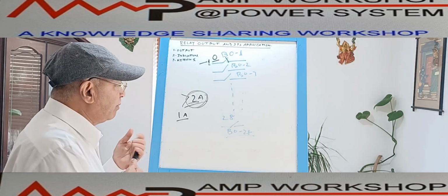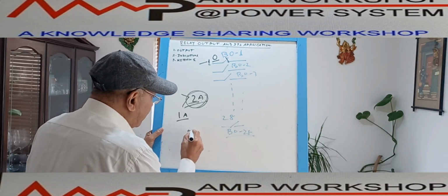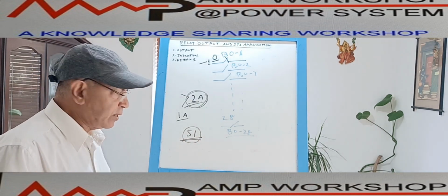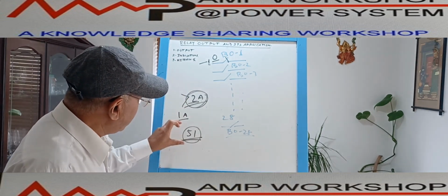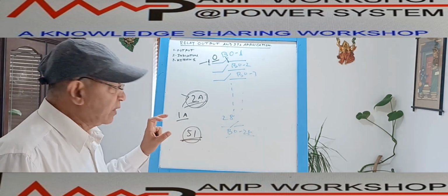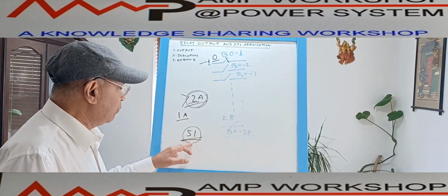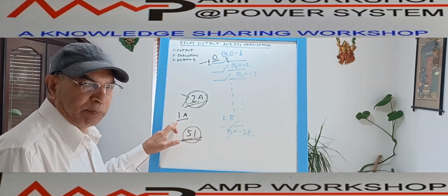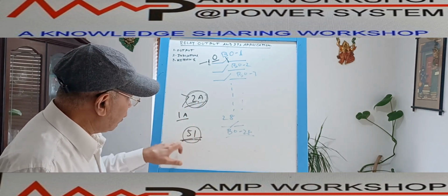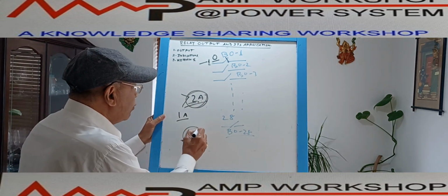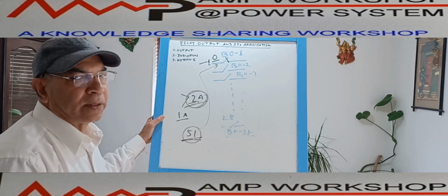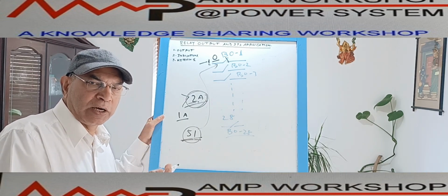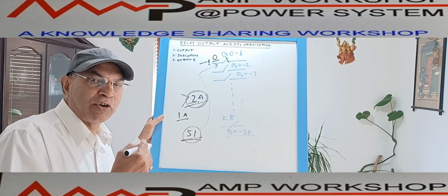Under that overcurrent condition, the IDMT overcurrent relay, that is the 51 function. As we have said, this protection relay has multiple protection functions. When the protection relay senses that the input current magnitude is more than the 51 setting value, which is 2 ampere for the 1 ampere input, the relay will immediately activate binary output 1, if we program it. As we have already said, the relay has software which can be configured or reprogrammed.